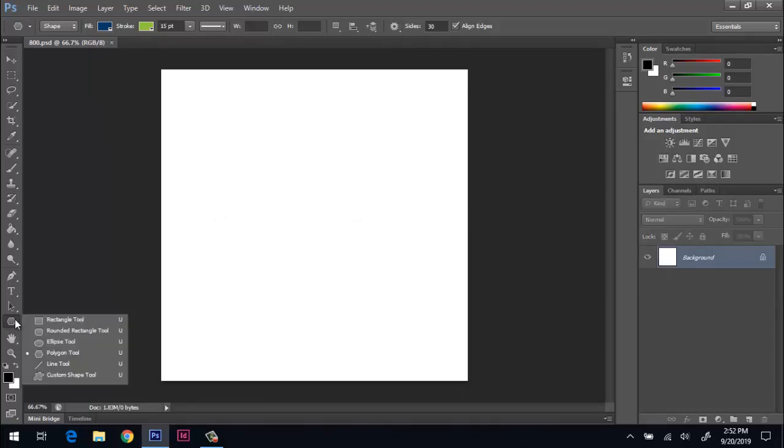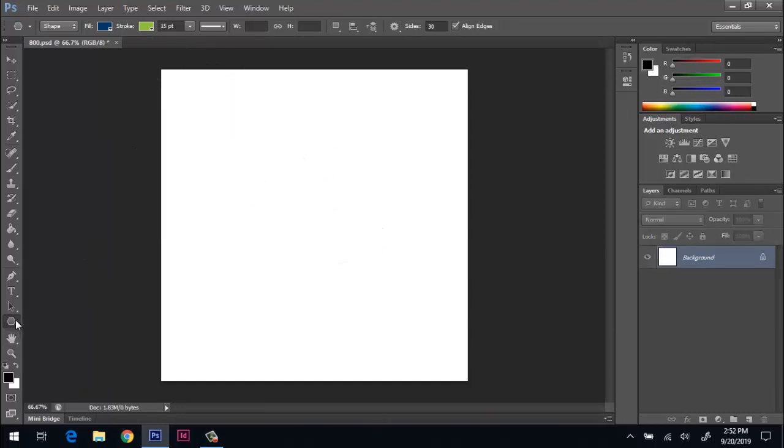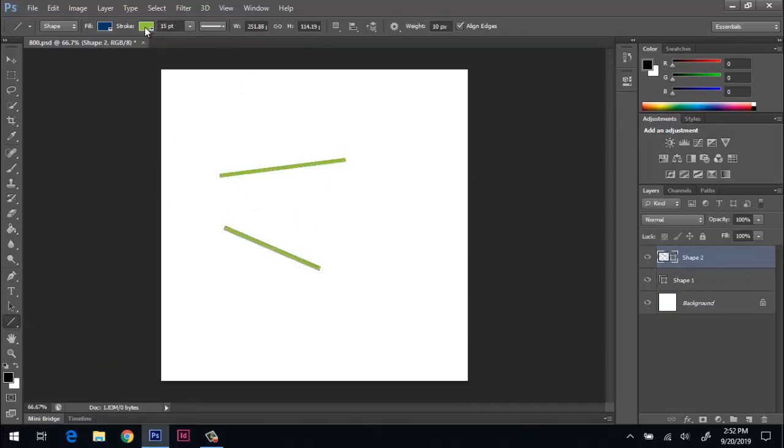And then we have the line tool. It's pretty basic. You can draw, whoops, turn the right tool on. Line tool, you can create lines, and it's based off of your stroke color up here. Now, if you want to draw a perfectly horizontal line, if you get close to horizontal and you throw down the shift key with it, it's going to lock it in at 0 degrees. And you can see the angle measurement in that little gray box to the right. It tells you the length of the line as well.